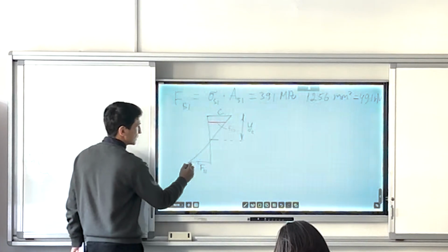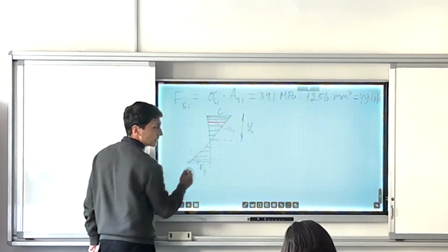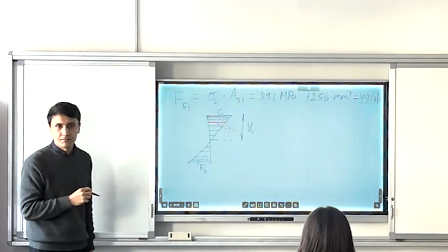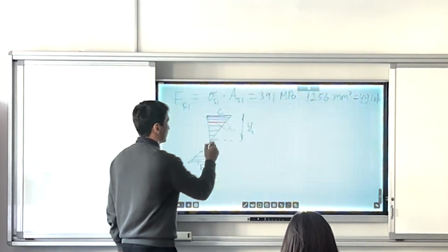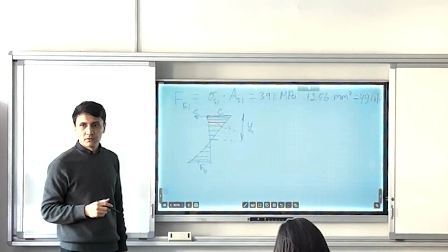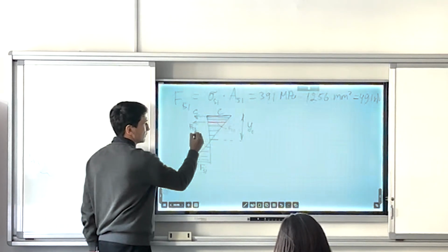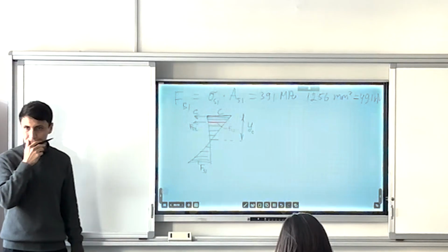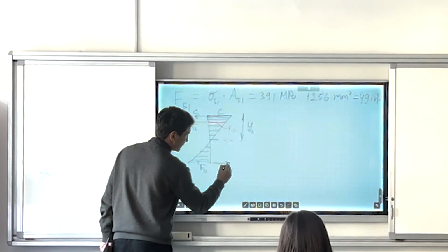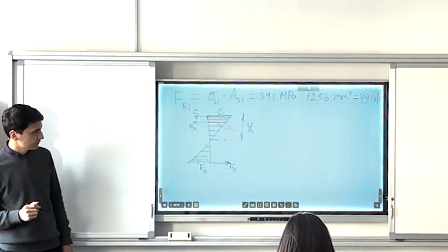So imagine this is your section. So you have neutral axis. This is the top fiber of concrete, and C is the force coming from the concrete. So let's assume it's compressive force, C, here. Then we have also force coming from the top rebar, which is Fs2, right? And now we have bottom rebar, which is force is directed opposite.